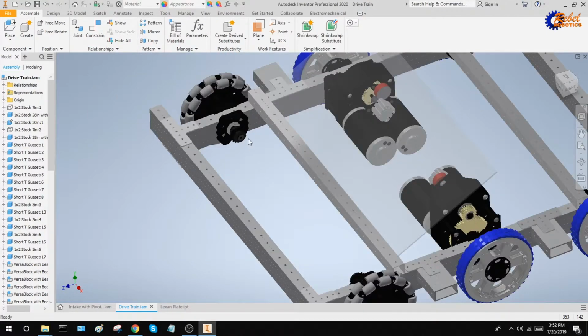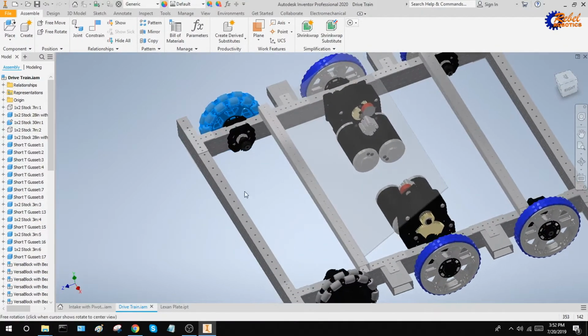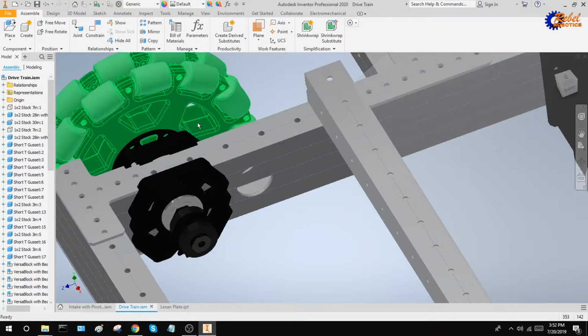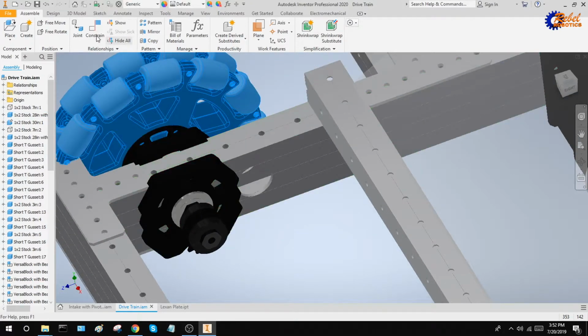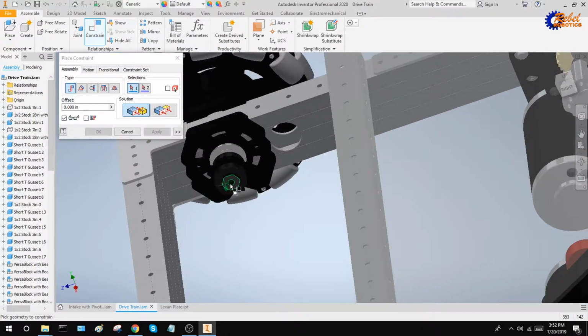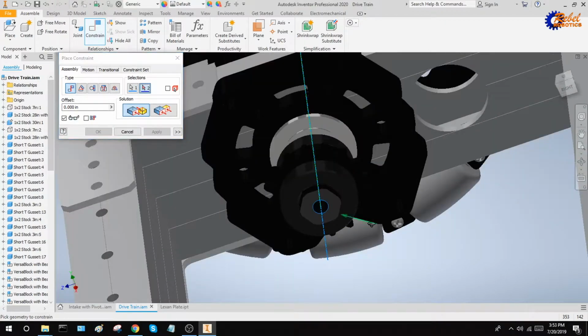In addition, let's say that I wanted to constrain this whole block assembly a certain distance away from this piece of stock. I could constrain the entire VersaBlock setup to this hole, but could also do another mate, where my first selection would be the axle of this hex shaft, the central axis.